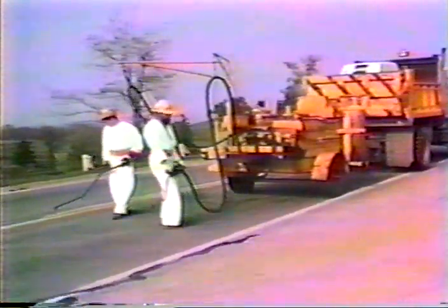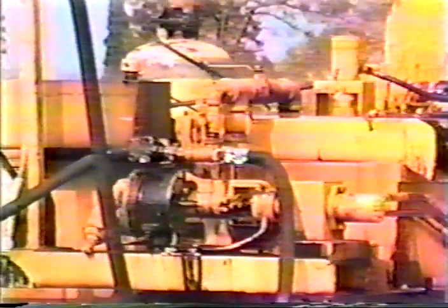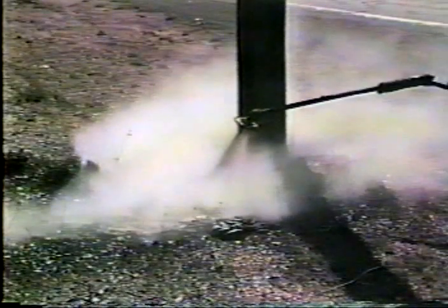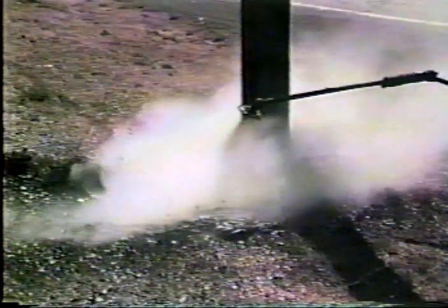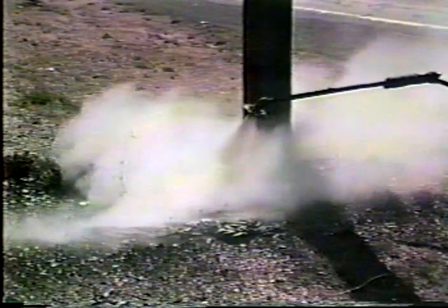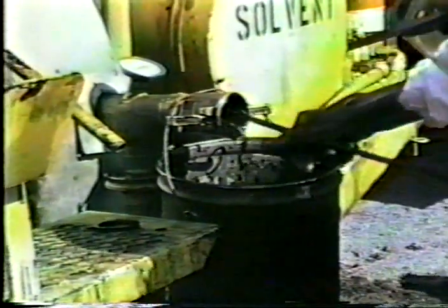Most kettles are equipped with an agitator to keep the sealant well mixed and a hydraulic pump that permits the application of the sealant through a wand. The kettles must have an agitator when an additive is used. Most units have a system to clean out the hose and pump. It is very important that the system be used at the end of the day. The clean-out operation should be done in an area where it will not be tracked, create an eyesore, or pollute the environment.